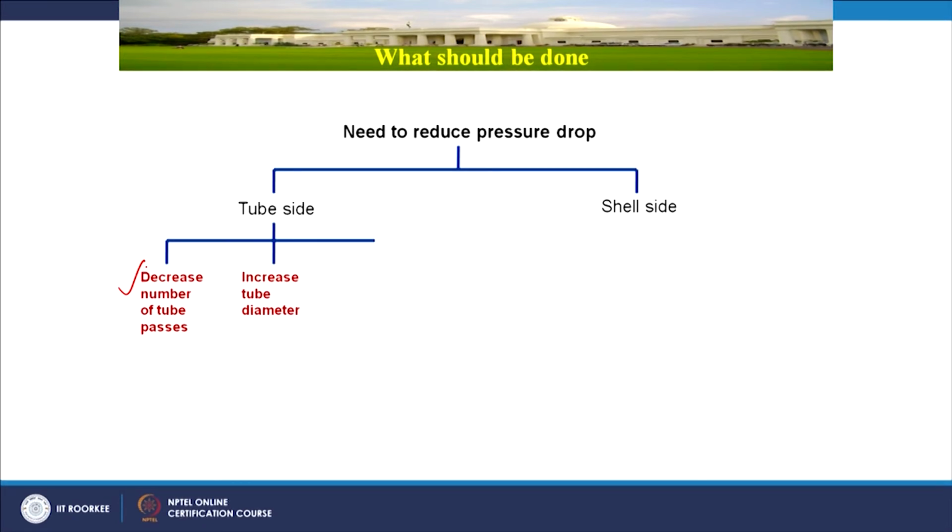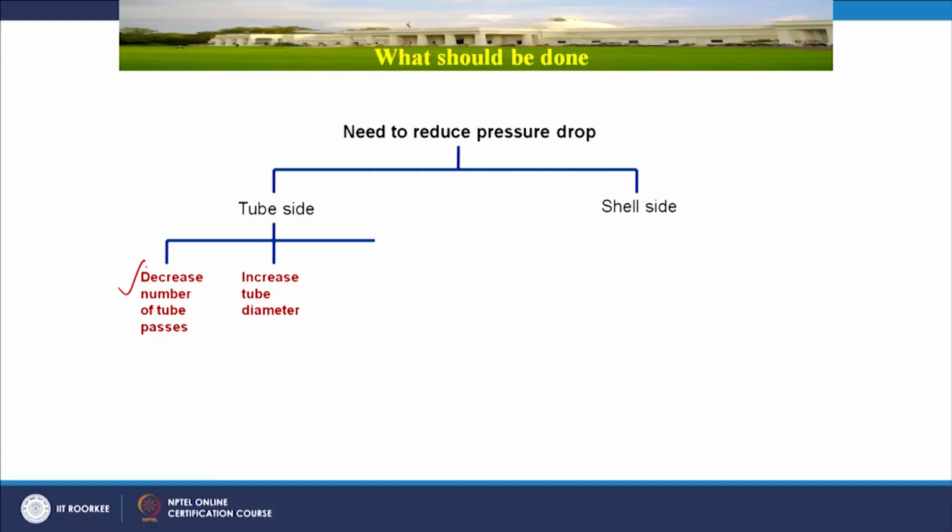So, if you are changing the diameter, the heat transfer coefficient will not differ significantly. All these changes, like changing the diameter, you can make as a slight change in calculations. But when you are changing the diameter of the tube, the pressure drop and heat transfer coefficient change will be very small. So, if less variation is required, then only you should proceed for that, otherwise passes will be the better option. I hope I am clear.